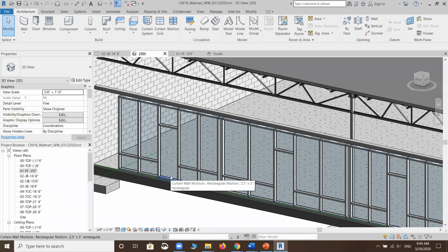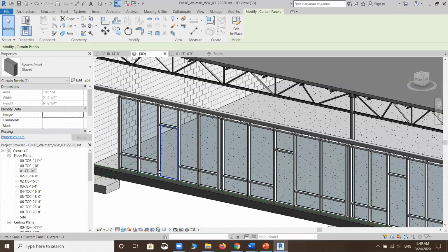Press the tab key, and it doesn't do anything. Press tab again, and now you see that panel being highlighted. It depends on where your mouse is. You may try it twice, three times, or four times, but you will know when you see the panel selected, because it will be highlighted in a bluish color on the edge. That's when you pick up that panel.